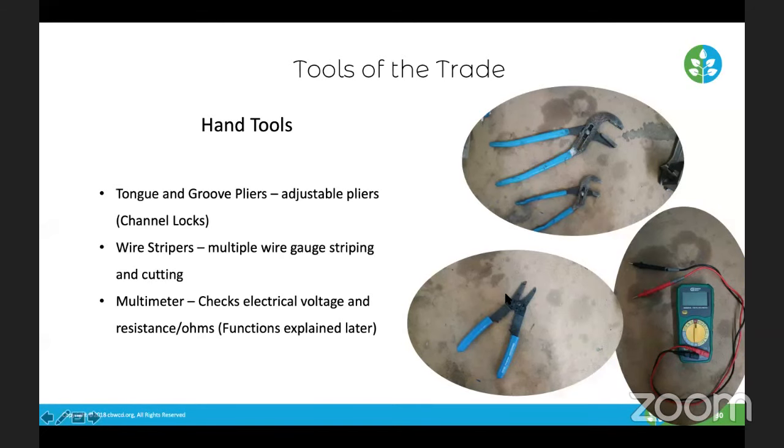We're going to cover a little bit about wire nuts and the importance of connecting the valve properly electrically. So stripping the wire, putting wire nuts on, cutting wires. That is definitely part of irrigation maintenance. So, light electrical work. As a contractor, you're not allowed to touch the 120, the power going into the socket. You're only able to work after that. If you have an irrigation controller, usually at home, it's a pigtail where you plug that into the wall. And so it's all relatively low voltage when it comes to irrigation.